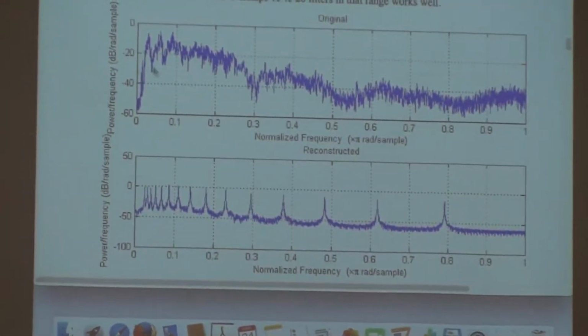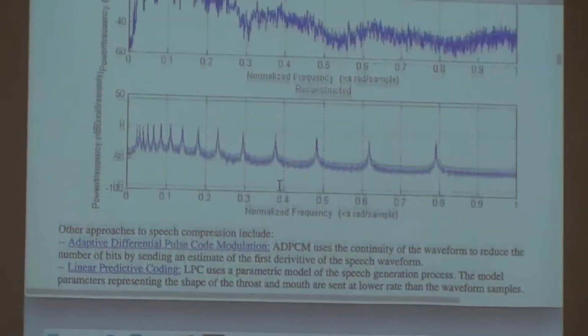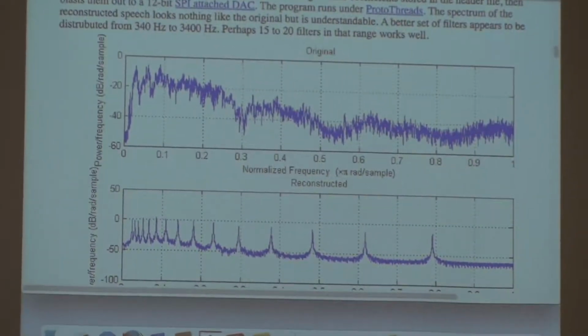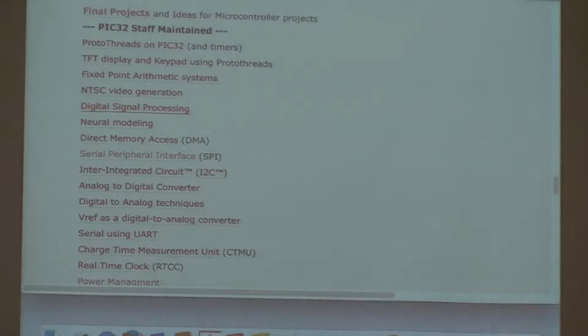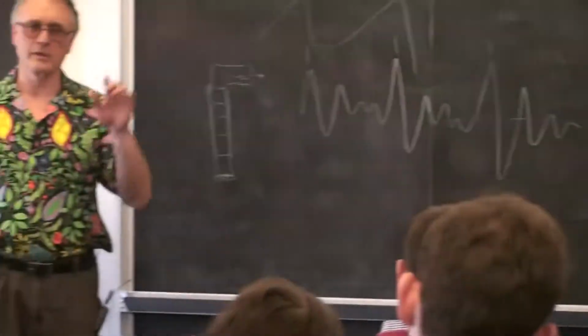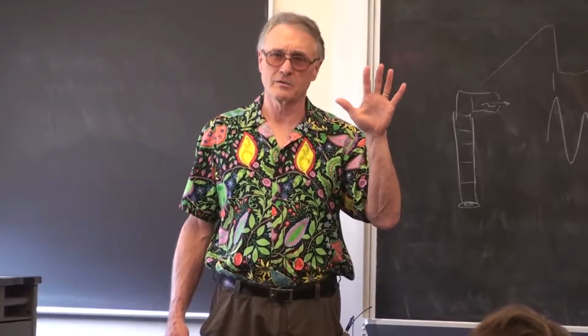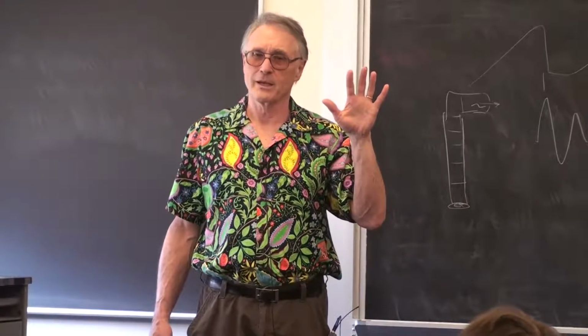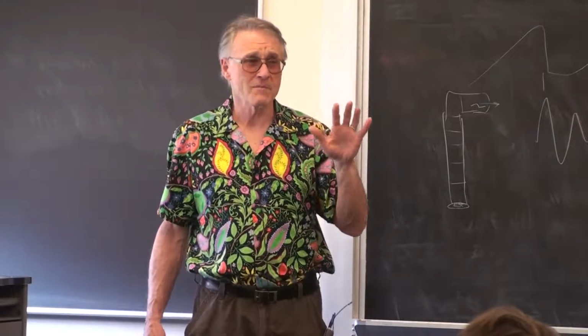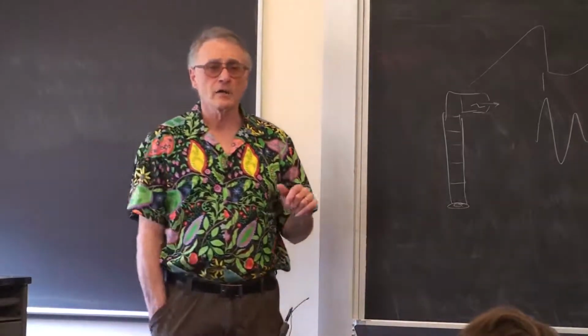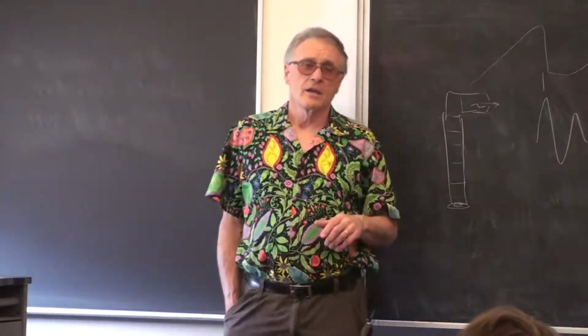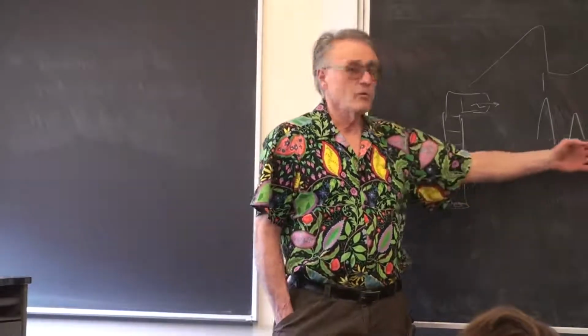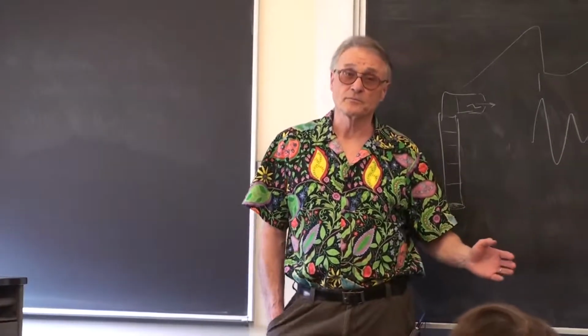By the way, this is the original spectrum, and this is what it looks like after resynthesis, and yet the spectra are grossly different, and you can still understand the speech. In fact, if you plot the maximum energy of the spectrum and use sine waves at the maximum energy of the spectrum, you only need 5 sine waves to make understandable speech. Nobody actually knows why this works, but it works. So yeah, an auto-tuner I think has some challenges, but there's lots of interesting waypoints also, like just getting the pitch.